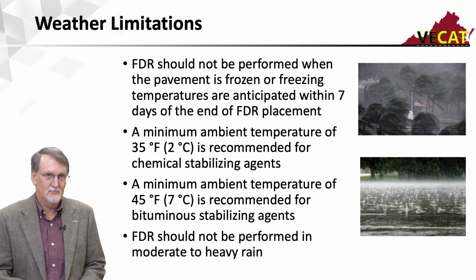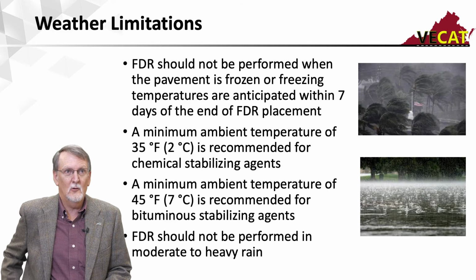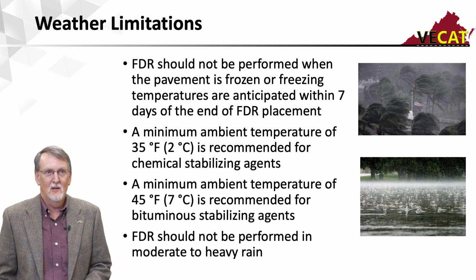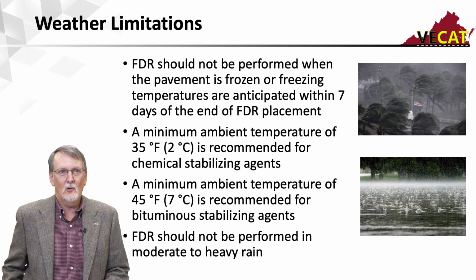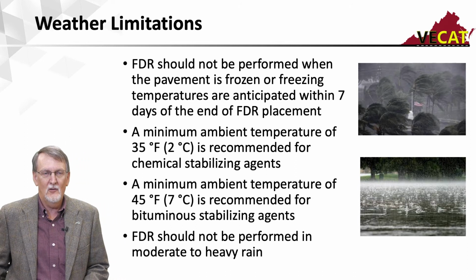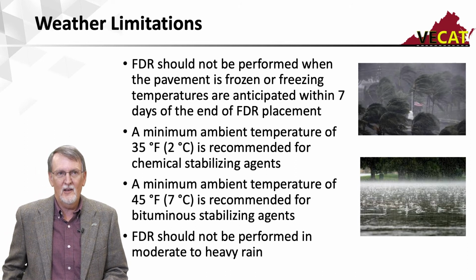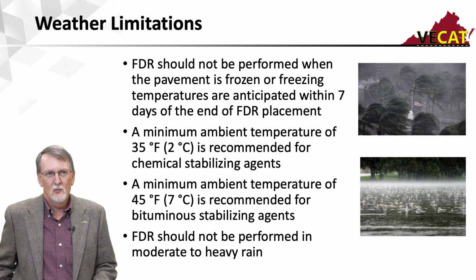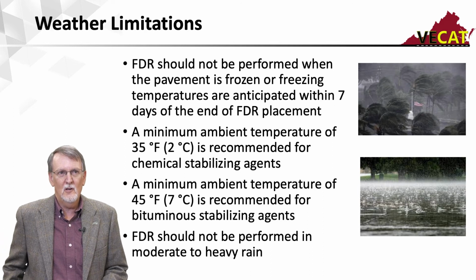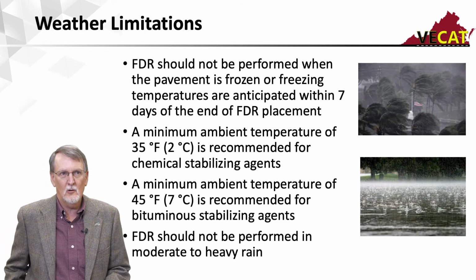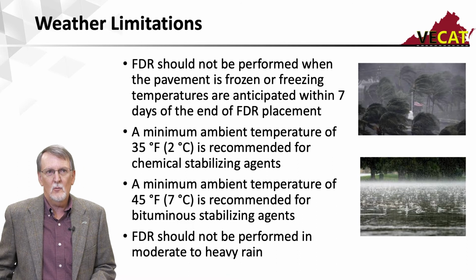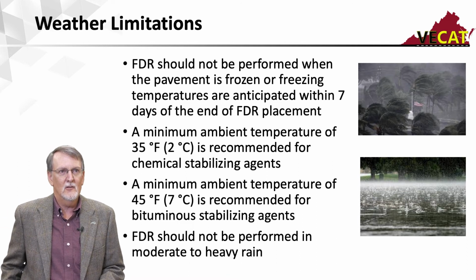Weather limitations. I don't want to do this when the pavement's frozen or when I have freezing temperatures anticipated within about 7 days at the end of the FDR placement. I want it to adequately cure. As far as minimum temperatures, with cement, or the chemical, you can go a little colder, so a lot of times we'll see 35 degrees and rising.